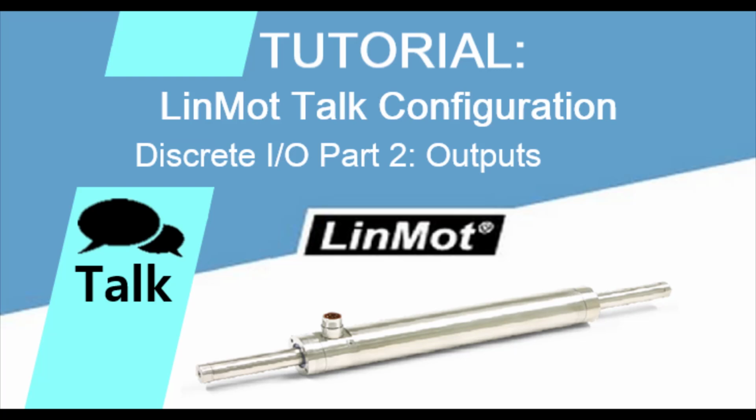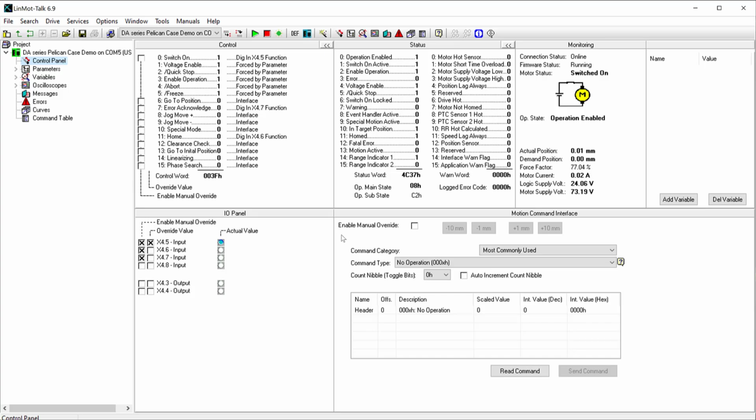In this video, I will discuss the process of configuring discrete outputs for your LinMot drive using LinMot Talk. If you have not done so already, please be sure to check out Discrete IO Part 1 for information on how to configure inputs for your drive using LinMot Talk. In the previous video, we hooked up the digital input on X4.5 to the switch on bit in the control word, home to the input X4.6, and error acknowledge to input X4.7.